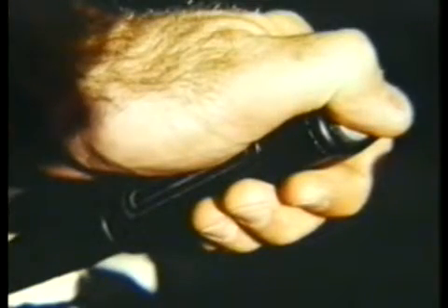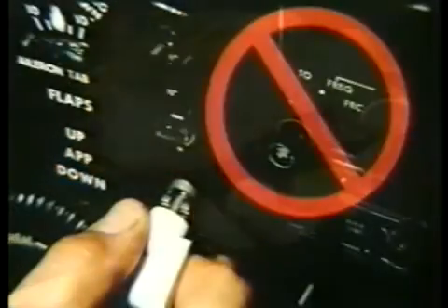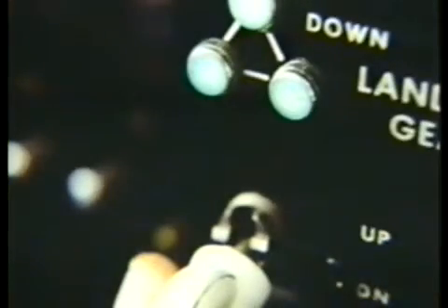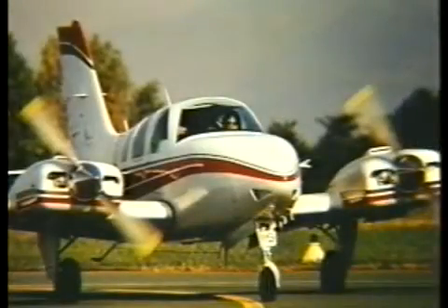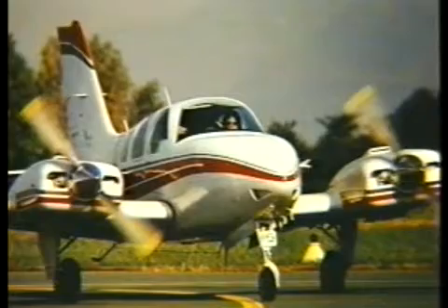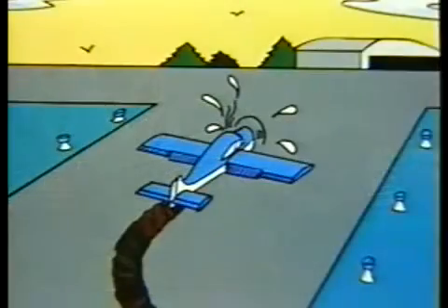First, some pilots' operating handbooks indicate that retracting the flaps will decrease lift, thereby putting more weight on the gear. It's really best, however, to wait on flap retraction until you're well clear of the runway so you can divert your attention to your checklist. Then you can concentrate on identifying the flap switch or handle properly, rather than taking the risk of retracting the gear by mistake. Look at it this way. By delaying flap retraction until well clear of the runway, you will even out your pilot workload responsibilities and avoid confusion. Besides, taxiing to the hangar with your gear up requires one hell of a lot of power.